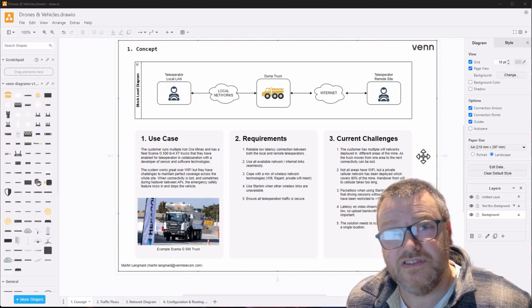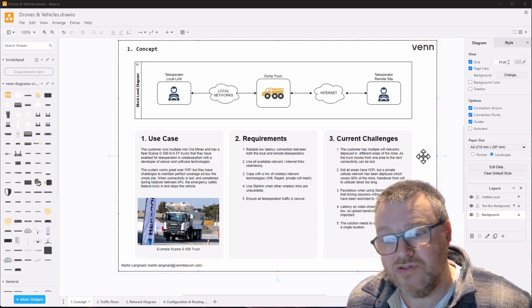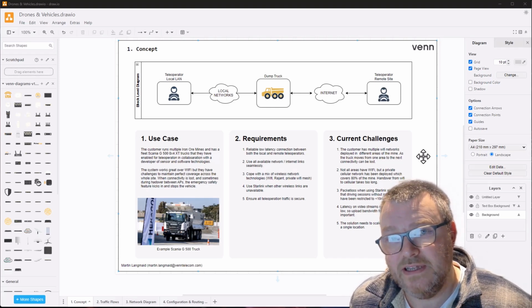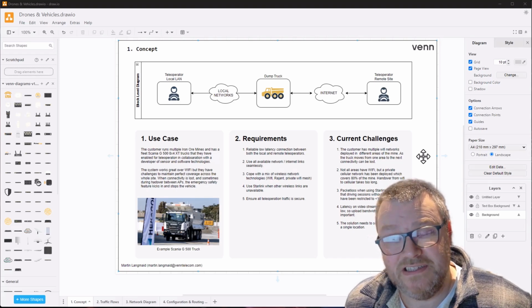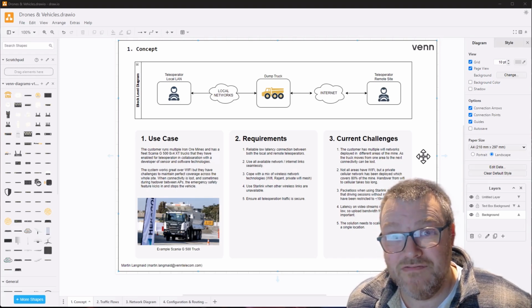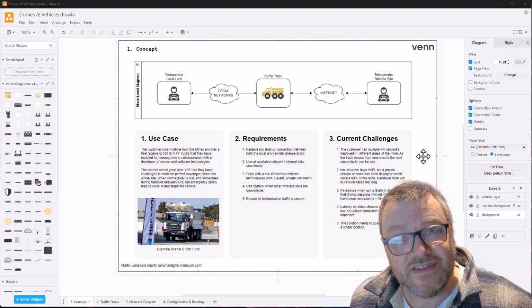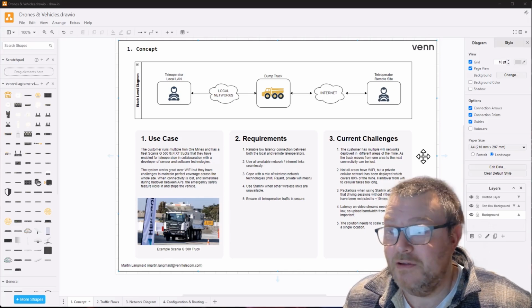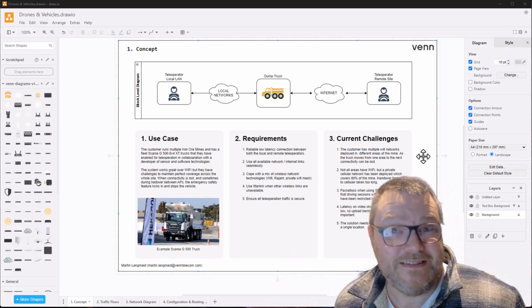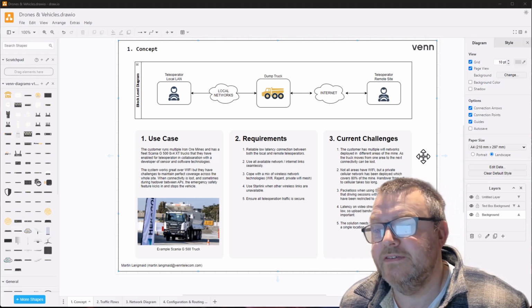When they tried to use Starlink themselves to remotely drive the dump truck, they struggled with the packet loss, the variable latency and indeed variable bandwidth that you see on Starlink in quite a regular sense. That impacted the latency on the video, and it's video latency that really impacts the ability to remote drive. As a remote driver, you lose confidence in the system if you get glitches in your video, or if the video suddenly is high latency on one screen and low latency on another, you don't trust the system. So it impacts confidence from the teledriver perspective.